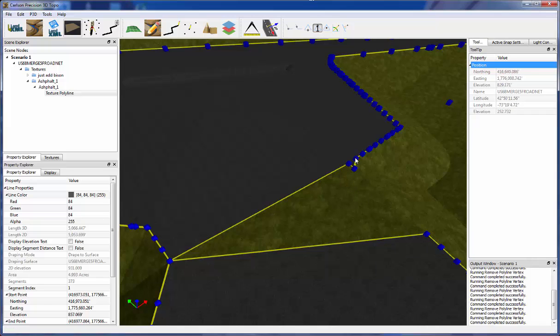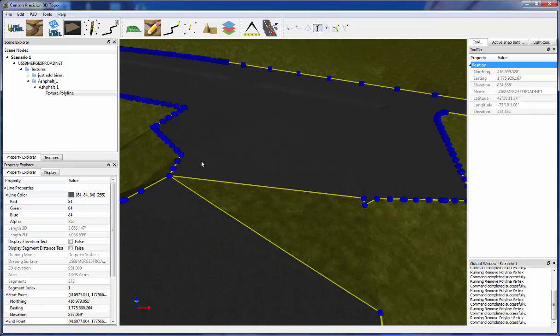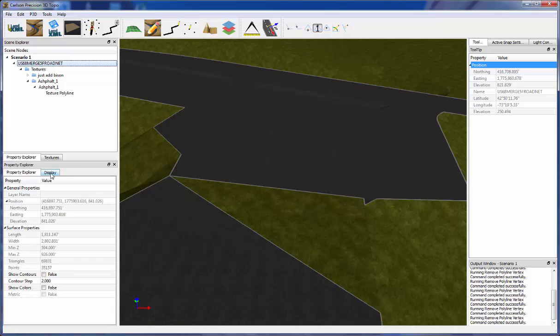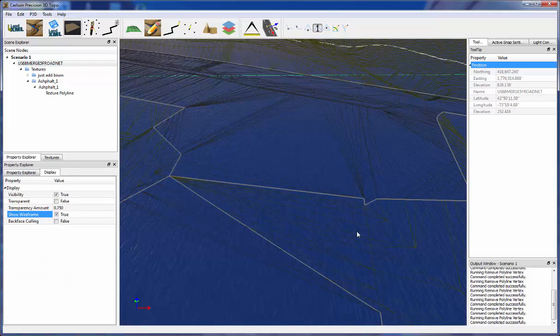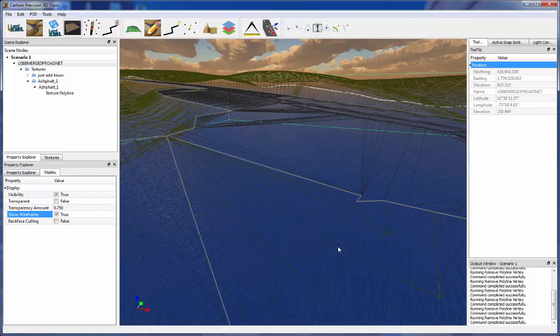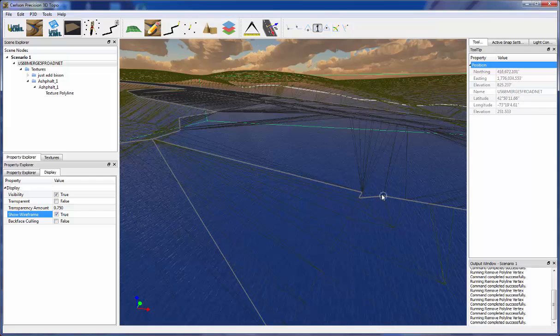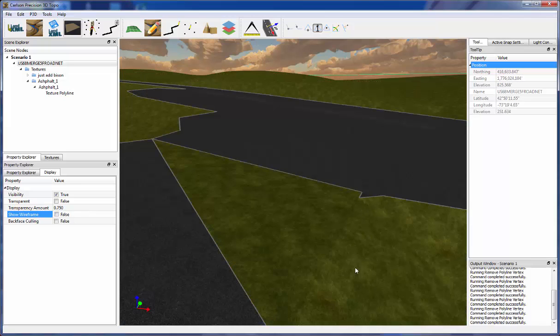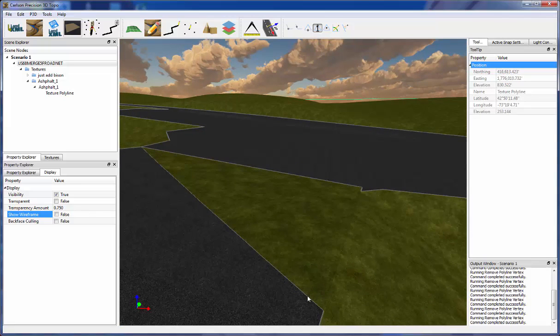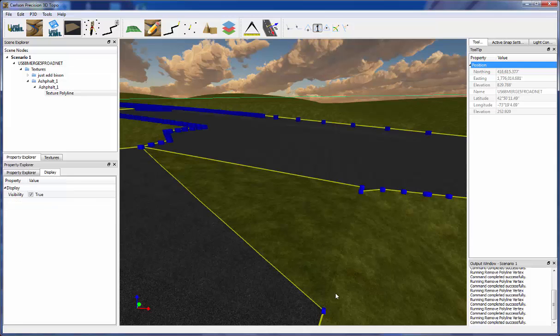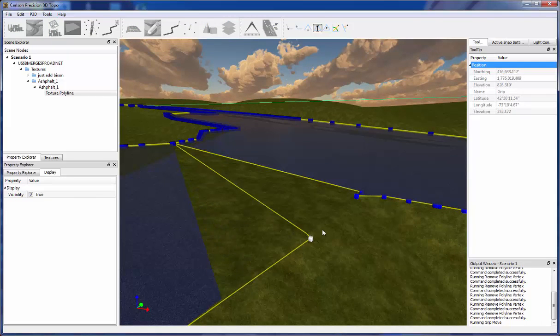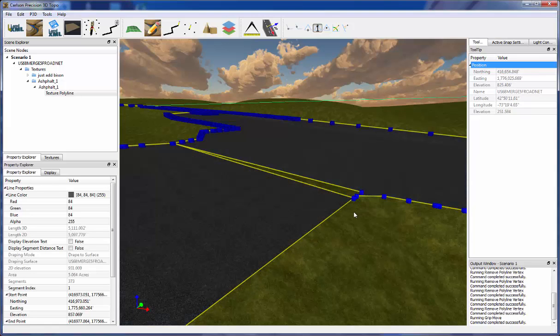I'm also going to turn on the surface node snap. So if I put the surface in wireframe, just to illustrate what we're snapping to, you can see that as I move my mouse cursor over a triangle face node, basically the points in the surface, you're going to get a nice highlighting effect for the snapping. So that's one of the ways that you can work in 3D without it being in wireframe and actually see this multi-textured environment and still be very, very accurate on your picks.